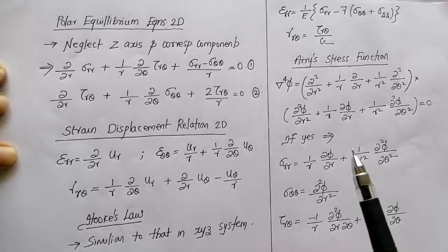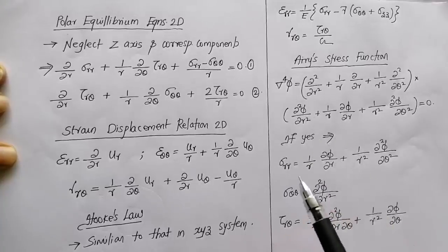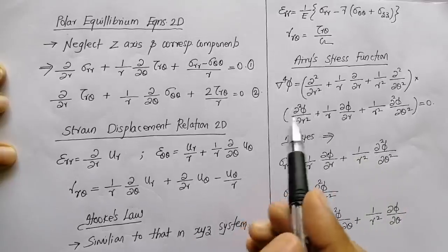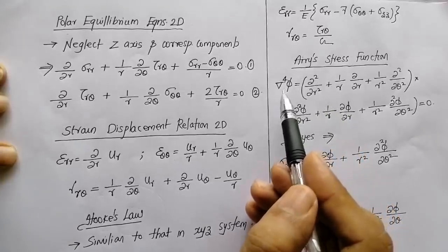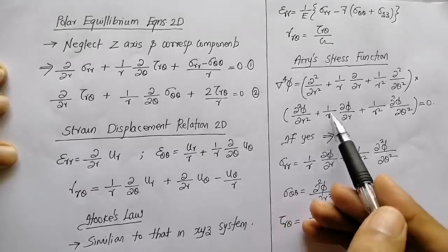How to analyze if it is an XYZ system? The equations will contain x and y. So, Airy's function basically contains 2-dimensional variables only. So, it will not be dealing with the 3-dimensional variables. So, here for Airy's function in r theta z, you have to check del raised to 4 phi equal to 0. So, what is the equation for del raised to phi here?